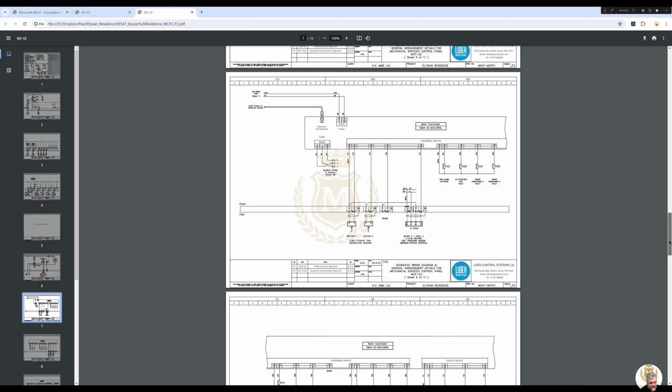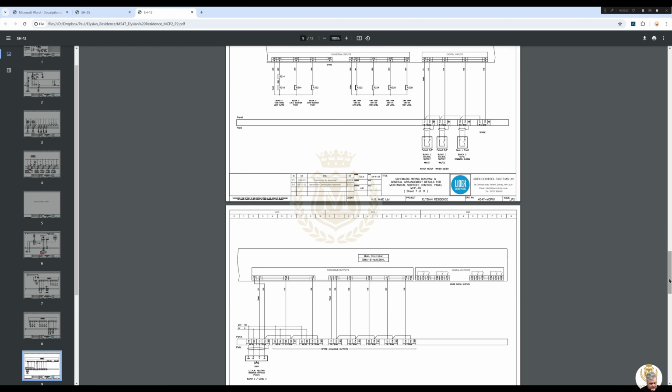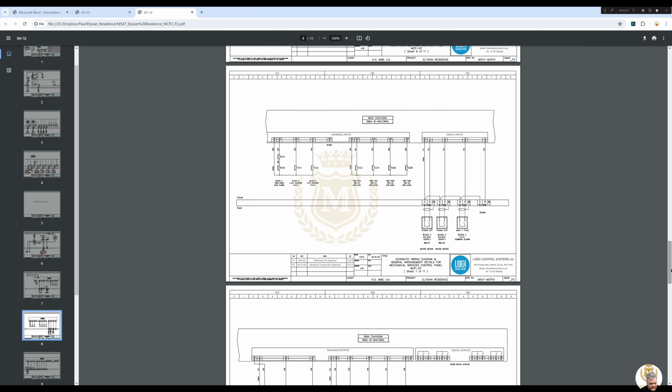Right, that's differential pressure sensor, 0 to 10 volts DC, going into universal input 4, so that's going to be the top of the riser, isn't it? And we're going to use that for pump speeds, I presume. Fire alarm, water conditioner, and what's this? Block C, water meter, pulsed.